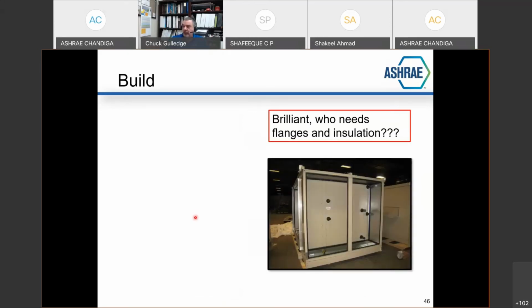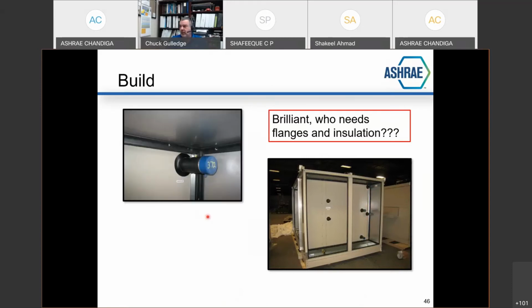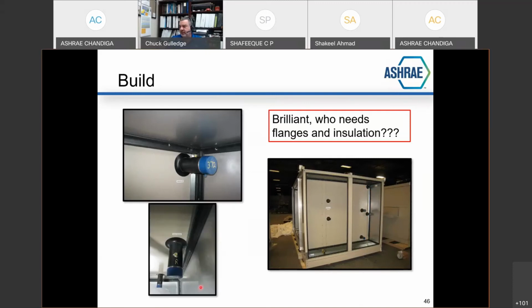Another modular air handler. These happen to be chill water coils, big unit, stacked chill water coils. Well, this might be an interesting development. That right there is a blow up of that. Look how close that is to the wall. That was 2.5-inch piping. There is no way to get a flange on this, to go to flanged piping, and there's no way to get in here and insulate this with, I think that required 2-inch insulation to get to it. How do you work on it?